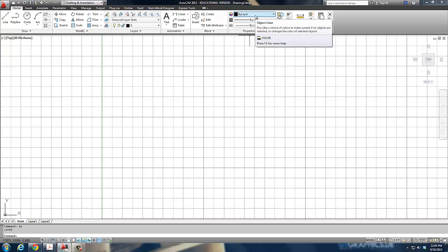Like if we're drawing a floor plan, our doors will be on a layer called first floor doors or first floors. Our cabinets will be on first cabinets. If they're upper cabinets, it'll be first upper cabinets. If it's like plumbing, it'll be like first plumbing. If it's first floor walls or first floor poche for the filling of the walls, it's first walls or first poche. And I mean, we try to make it make sense, to make everything so it is logical and intuitive to the viewer and to the operator.